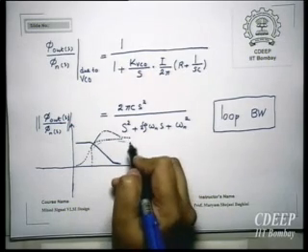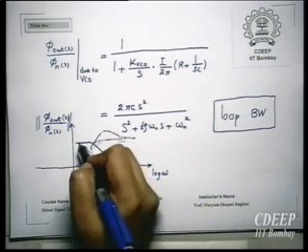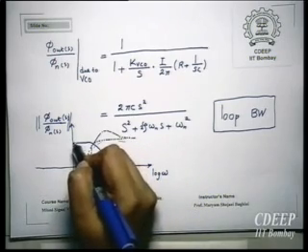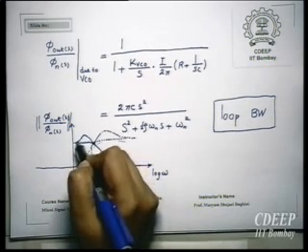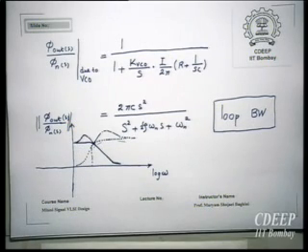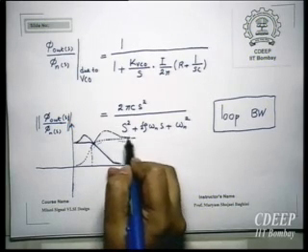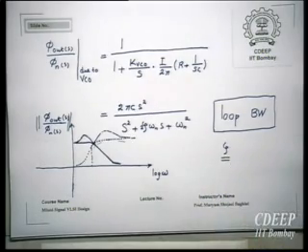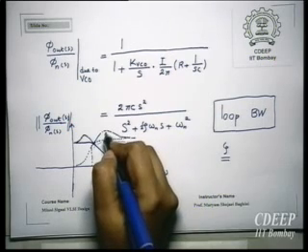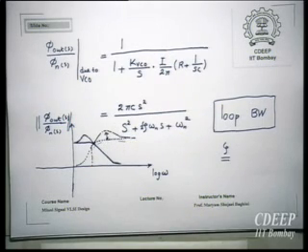This is the high pass filter. And eventually even the low pass filter will also have some peaking. Right? Therefore this is something which is called peaking in jitter. It means that it not only passes but also amplifies jitter. Therefore it is very important to see what this value of zeta will be, which determines the amount of peaking, which also will determine jitter peaking.